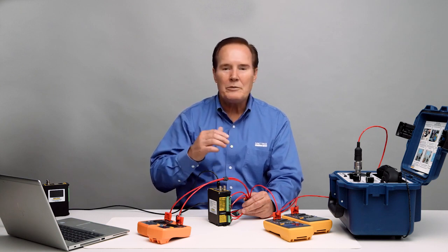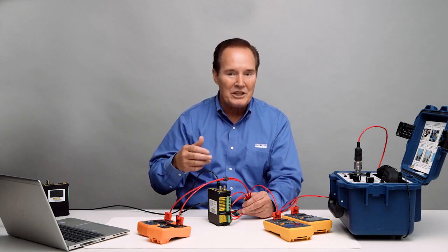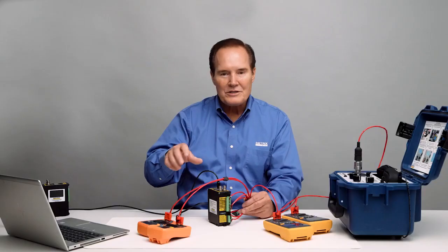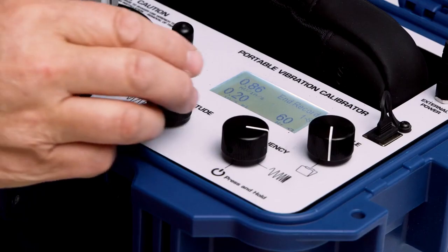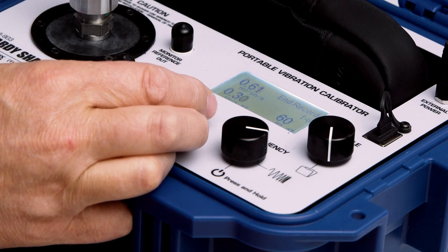We'll go to 0.3. We'll have the 0.25 inches per second alarm come in. We'll see that with a flashing yellow light. And then we'll go up to 0.6, and we'll see the danger alarm come in. On both of those, we don't have the voltmeters connected to the relays, but when we switch to acceleration, we'll see that. Let's go ahead and increase this to 0.3 inches per second.